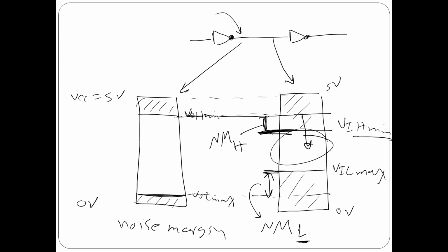I think one of the questions in chapter 2 is about why we need to know the propagation delay. For sure, the propagation delay is going to tell you how fast you are going to get the output. For example, if you have a delay here of 1 nanosecond, and I apply input here, how much time is it going to take until I get the output here? There is a delay here and there is another delay here. So if the delay here is, for example, 1 nanosecond and another 1 nanosecond here, in total it's going to be 2 nanoseconds. Okay.